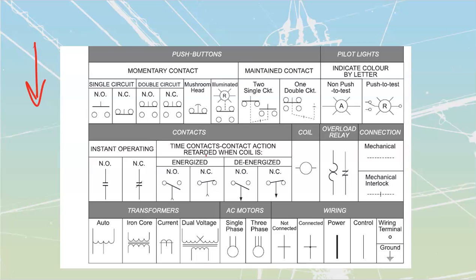Maintain contact switches are going to have an activator that is going to pop out one button when the other button goes down. So this over here, that dotted line, is indicative of a fulcrum, having that little piece there in the bottom. Basically, if I would push this one down, then that is going to push this one up, and vice versa. When one goes down, the other one would have to mechanically be changed out. That dotted line refers to mechanical interlock, as it's called.